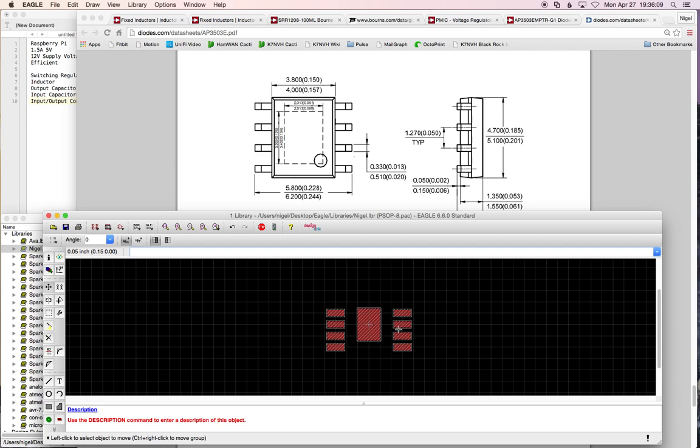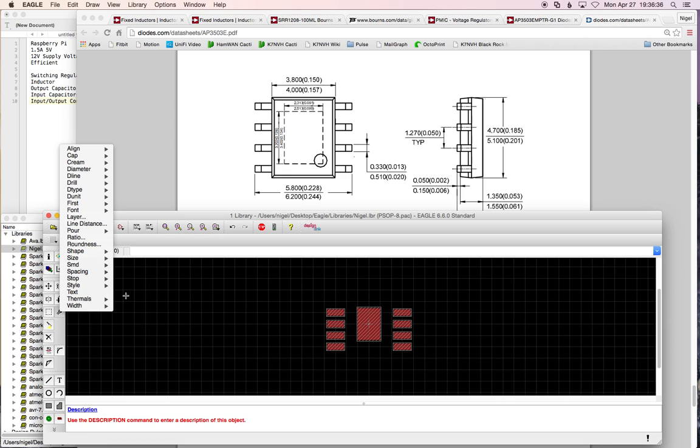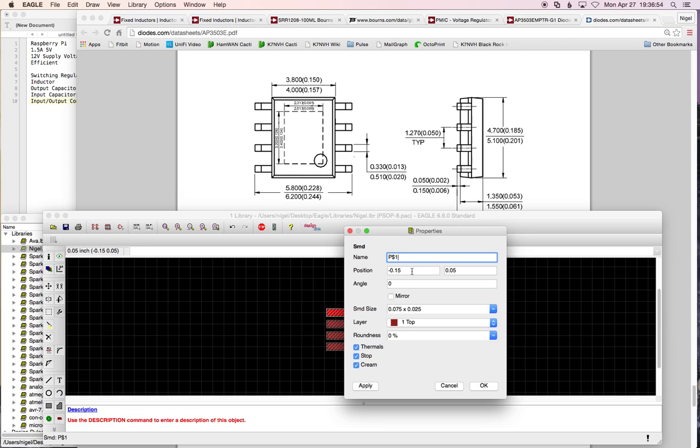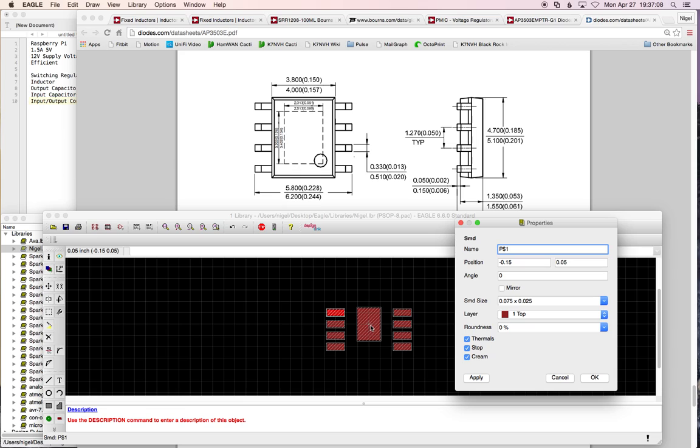So we'll deal with the horizontal adjustment in just a minute, but what I'm going to do is grab the group of these and right click the group and, where's my properties? I don't know. I'll just do it manually. So I'm going to change these to be offset by another half step, between these 0.05 increments in the vertical direction, so that when we look at the center of this center pad, instead of going right into a pad, we go right between them.